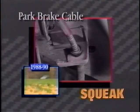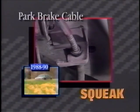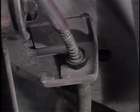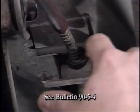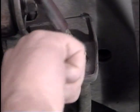Park brake cable movements through the grommet in the right side cable support bracket can also cause a squeak or squawk noise. This condition can be easily remedied by applying a good quality lubricant to the cable where it passes through the grommet.